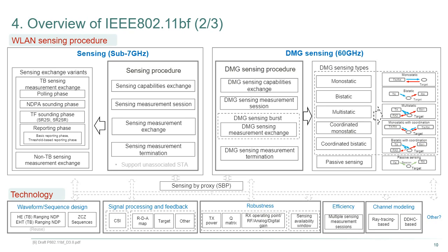Yeah, I think the answer could be important for both sides. So, starting from the end, finally, we would like to get a measurement which is stable and robust, right? So we would like to confirm whether some change or variance of the channel state information (CSI) is from the environment changes or from the TX/RX changes, including transmit power, beamforming, and also AGC level changes.